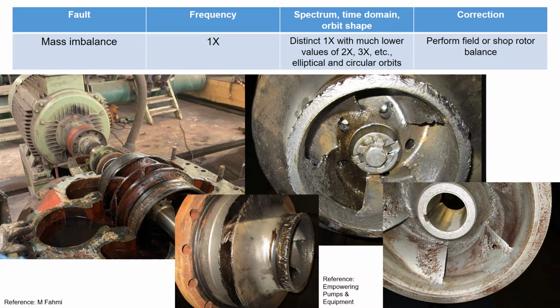Machine can be subjected to significant wear and tear over time and can experience an increase in 1x vibration due to mass imbalance. If the vibration increases too much, parts may need replacement and field balancing may be required.